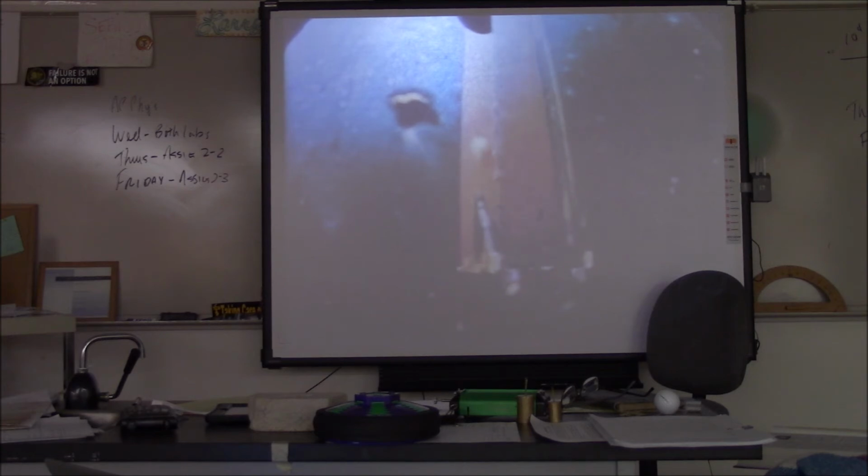The escaping gas applies a rotational torque to the tank, causing it to slowly spin. This tumbling motion prevents aerodynamic skipping off the atmosphere and ensures the correct re-entry trajectory. Because if it wasn't spinning, the tank would act like a rock that hits water and skips off the ocean. As part of the pre-flight, by making it spin like that, it's going to break up and burn up in the atmosphere.